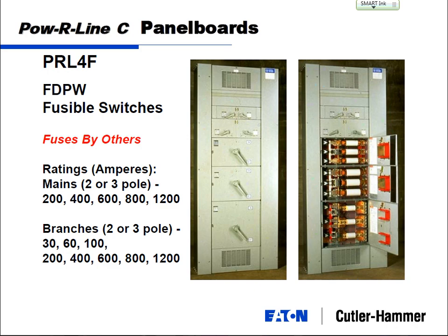Now, when you are working on a piece of equipment like that, and you pull the fuse out, this is energizing the board on one side at least. Yes, if you asked us how to replace that fuse, we would tell you, you go upstream, like you mentioned before, to the main switchboard to isolate this completely, so you can get in there and grab onto those fuses. A lot of old-time electricians say, I can do it, until it only needs to happen badly once. Arc flash. You've got to remember that.